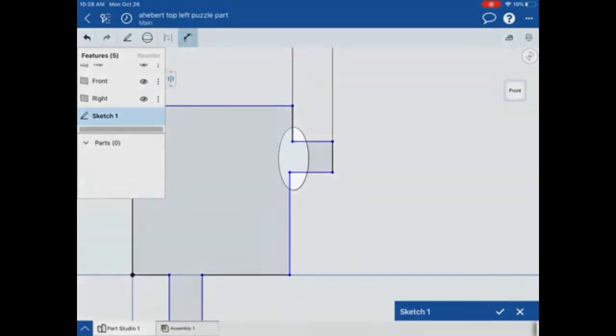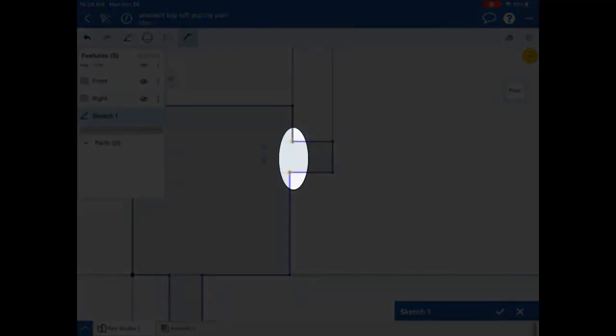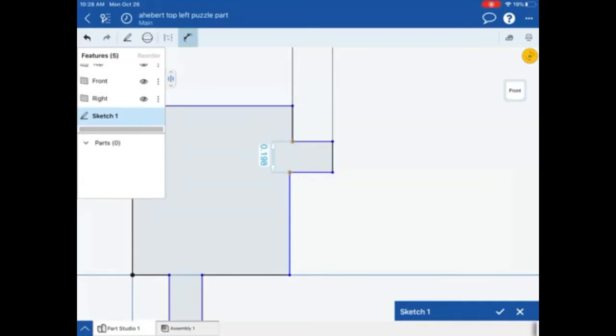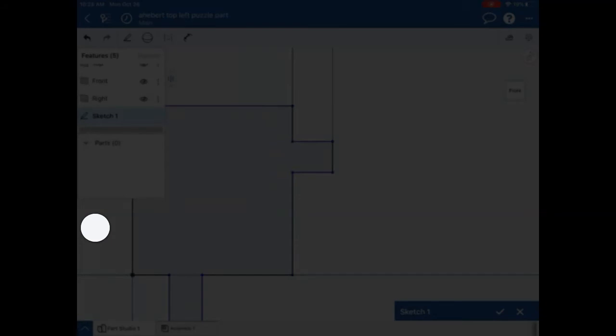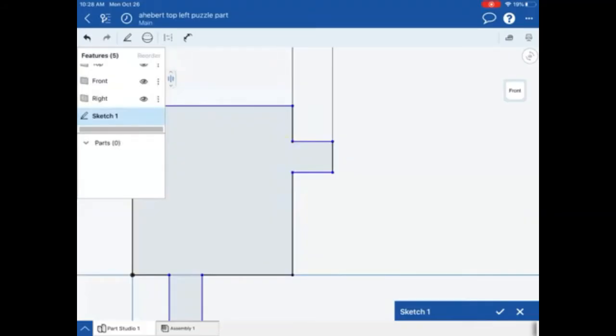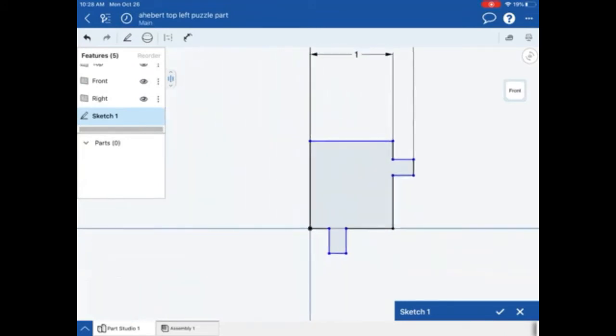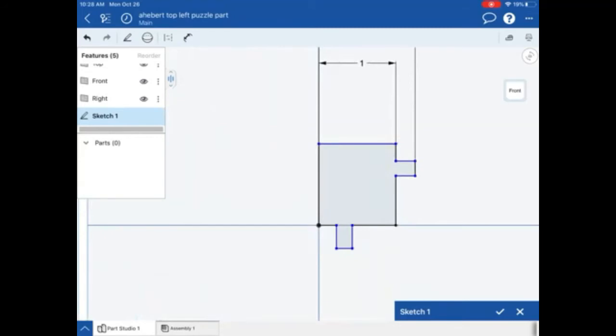Now, if you notice, it didn't move the points below. If I want, I could say I need this point and this point to line up vertically, right? Oops, it started to dimension it. Let's turn off that dimension tool. If I click those 2 points and I want them to line up vertically, I can go to my pencil tool and select vertical. Okay. Now notice both of those lines are black now, and they're lined up. Black meaning they've been dimensioned. They're located.